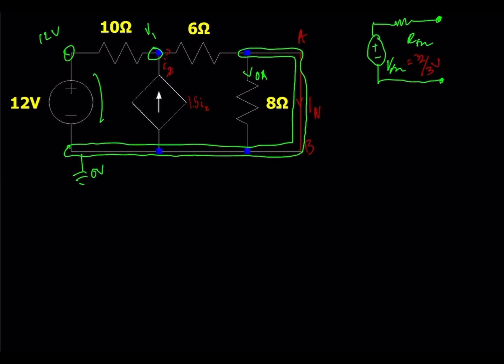Again, just as a reminder, KCL, Kirchhoff's current law, states that the sum of currents entering a junction is equal to the sum of the currents leaving. So whatever configuration there, it's just an application of conservation of charge. Charge can't be destroyed. So here we're going to start at our unknown node, here V1, and we're going to define the currents as exiting the node.